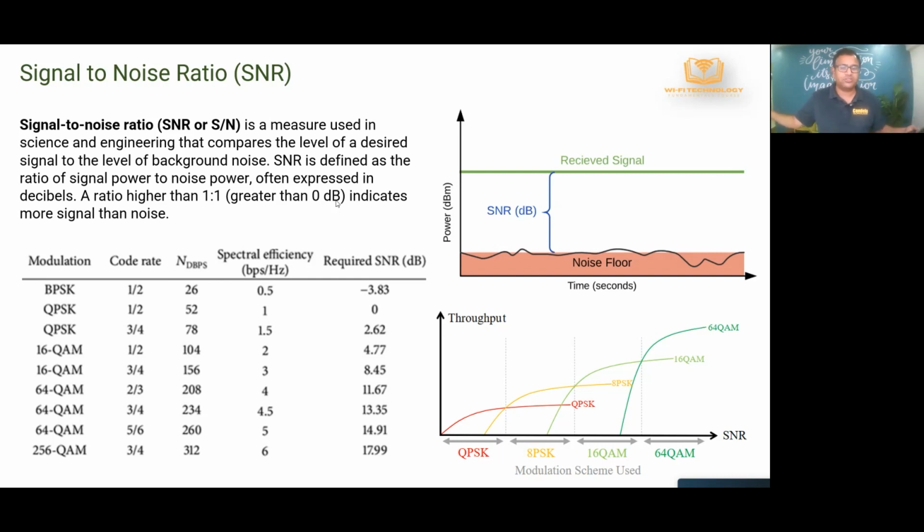So now what I do is, instead of using 16 QAM, which needs a higher signal to noise ratio, because remember that it has lower margin for error, which means that it needs a better signal to noise ratio, right? So I say, okay, instead of transmitting 16 QAM, I will give up some throughput and I'll go down to BPSK, right? And this is what's called rate adaptation or rate scaling in Wi-Fi. So as you can see here, BPSK, which is the lowest modulation rate, can live with a very low SNR. But as you go to the higher modulation rates, you need very high SNR.